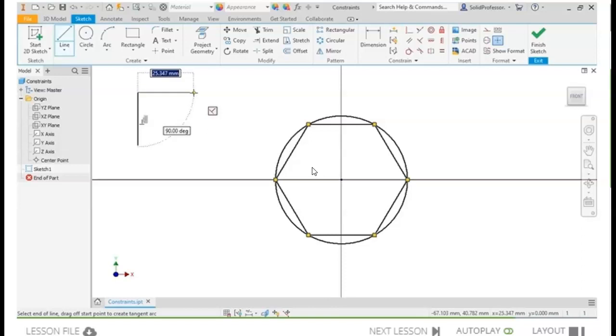These automatic constraints are extremely helpful when creating initial geometry. You just need to make sure that you want the constraints that are being added, so you don't wonder why you can't move a line as you want later. I'll undo the line placement and leave the circle and polygon's last dimension unconstrained for now. Because while it is possible to fully constrain a sketch with just constraints, I'm not able to set the circle size in this sketch with them.